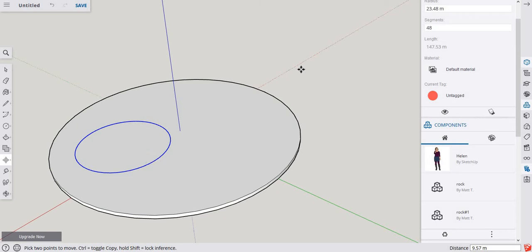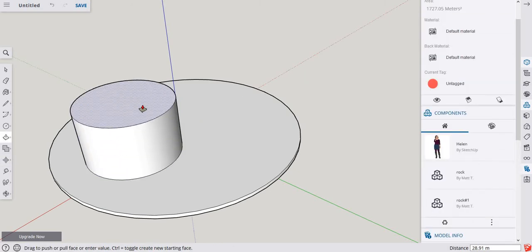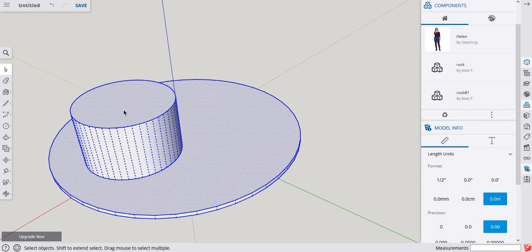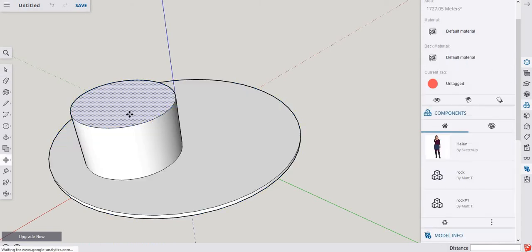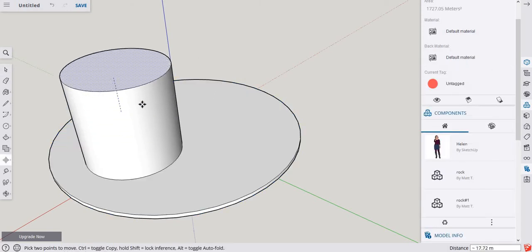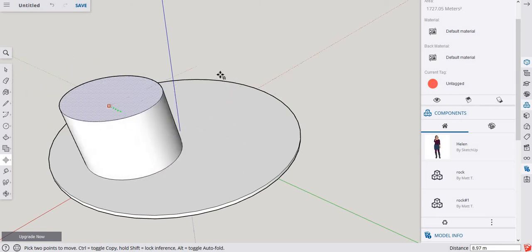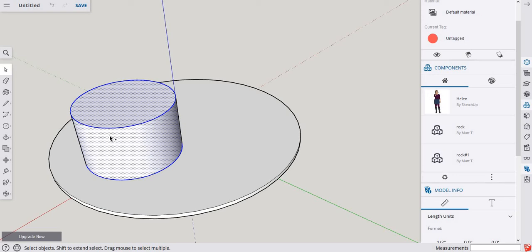Okay, so now, whoops. Let's move it there. Let's push-pull tool. We get what we call sticky geometry. So if I only wanted to select this cylinder, notice how when I triple click it selects everything. So if I want to move that face, I can move up and down, but when I try to move this way, okay, so double click, hold shift, double click.